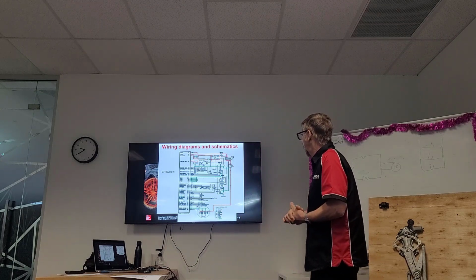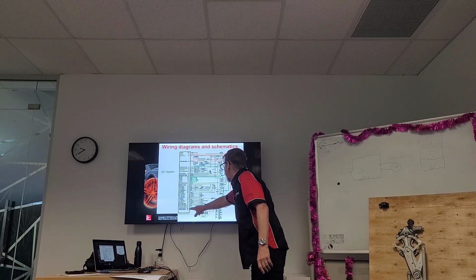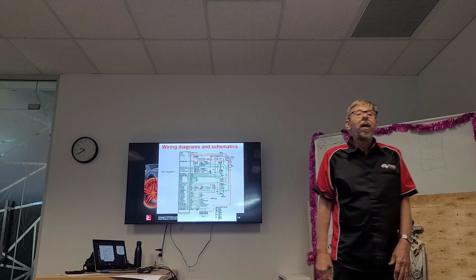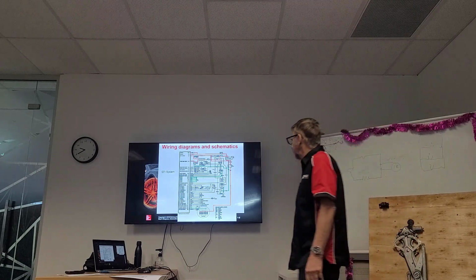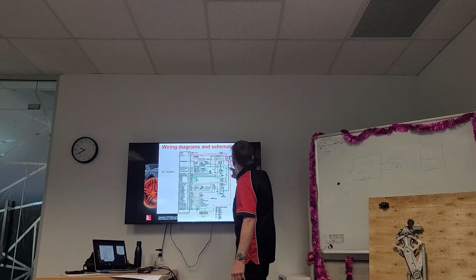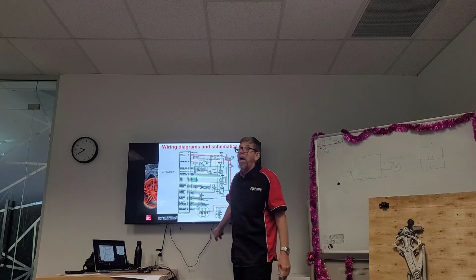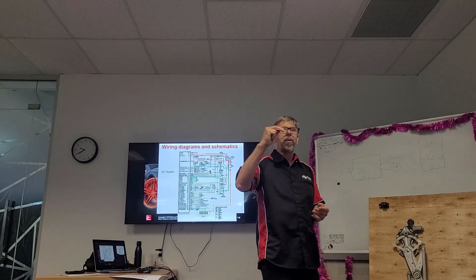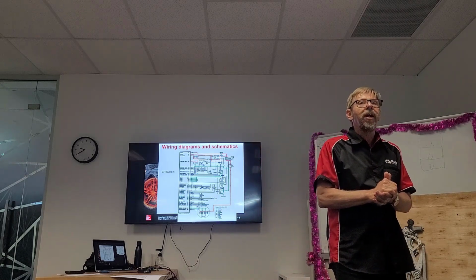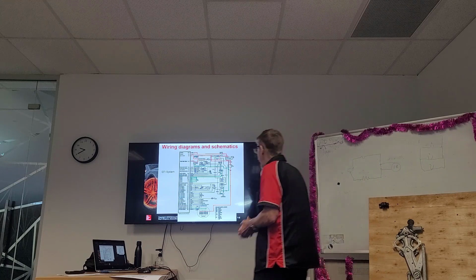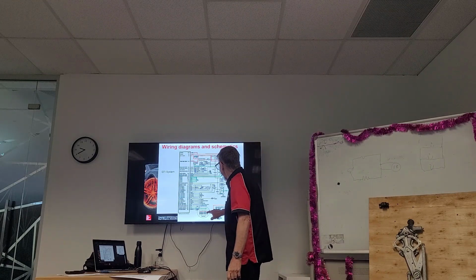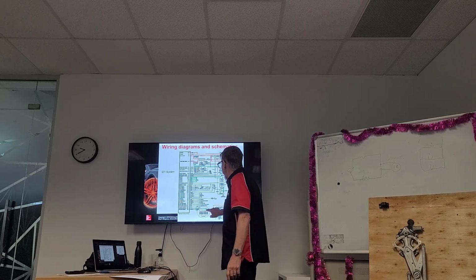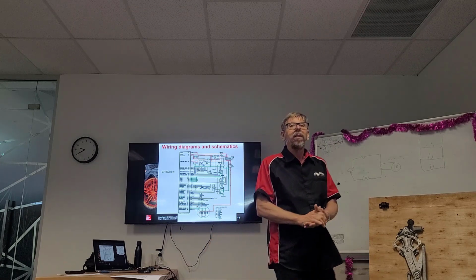Okay? I also have some grounds here. How do I know these are grounds? I've got a different colour. Because I have power when this relay's on to my injectors, and you notice all those powers are all consistent. They're all in the one circuit, okay? And I also know that to complete the circuit, I need a ground. So I have a ground, yes.